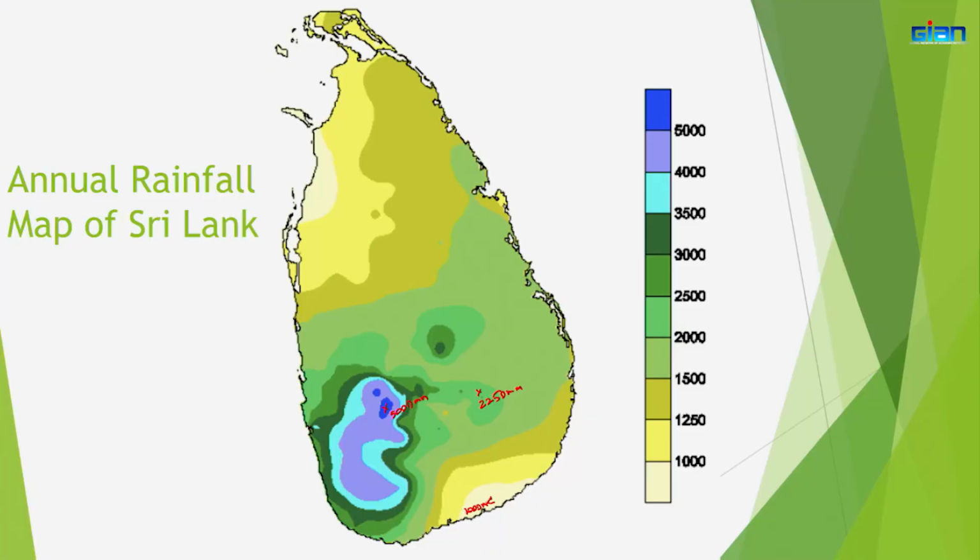You can call them and get the annual rainfall and get the average of those 4 rain gauges, rather than going by this approximation, because these are very rough, but actual measurements will be much better. So this is the worst case, we use this, but if you are lucky we can find close by rain gauges.